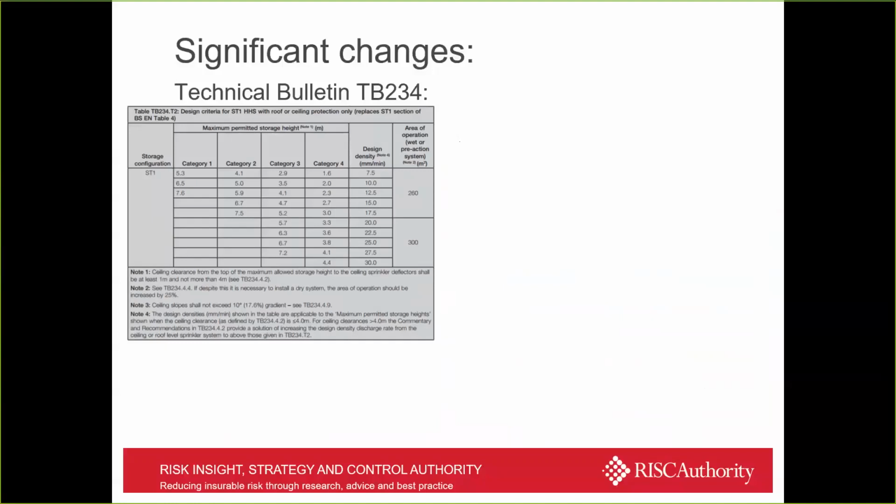As soon as you go over the 8.1, the first metre or part metre over your 8.1, you'd increase that 12.5 by 2.5 millimetres per minute, so that would go to 15 if it was within 1 metre more than the 8.1. Any further metre clearance over that, you'd add another 1 millimetre, and that would determine what your density would be.